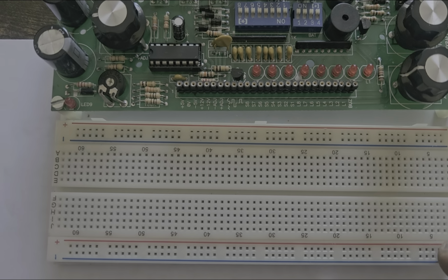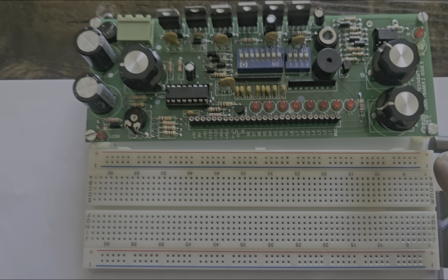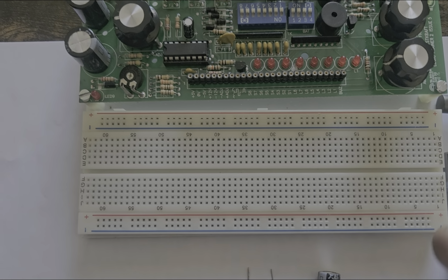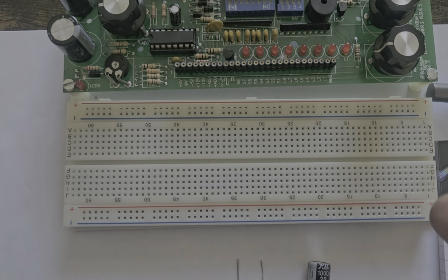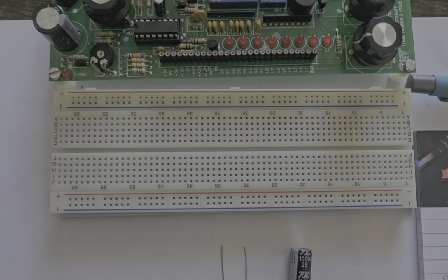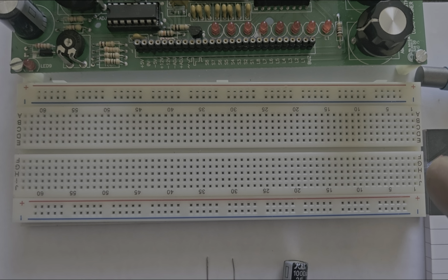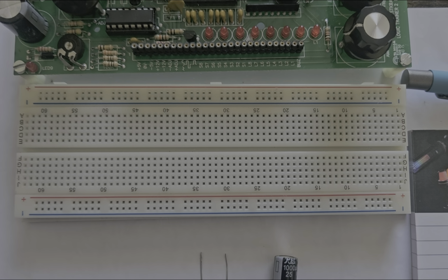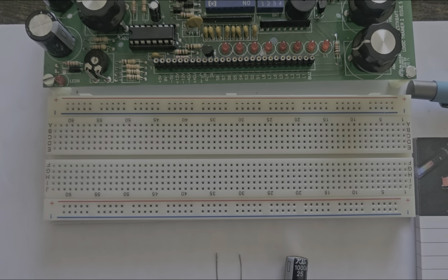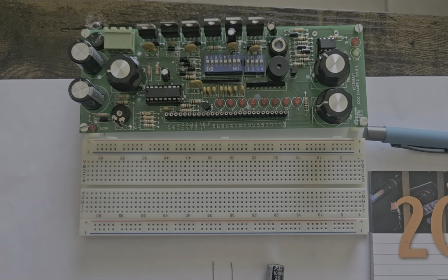Let's say you are powering it from a battery or from a DC power supply. You can use this power rail. You can also use the other power rail on the other side. And then you also get the component rail, which is the middle one. The way these are wired, they are not horizontal like this, but vertical. So there's a connection between point J and point F, between point E and point A. So if you want to connect something on this side, then it automatically connects to this line, if you get what I mean. So these are basic electronic components.